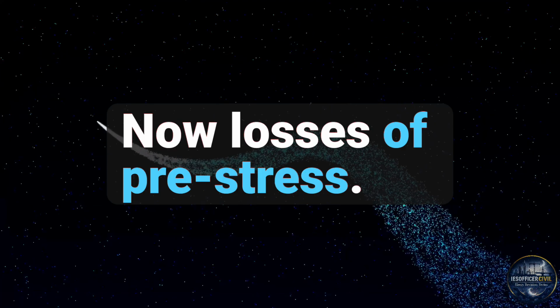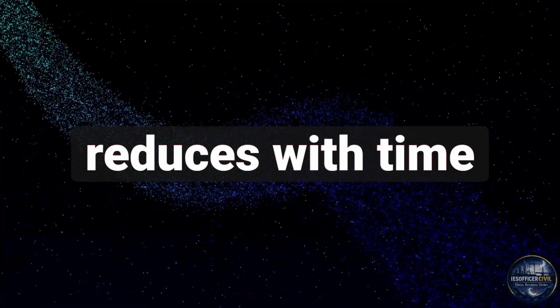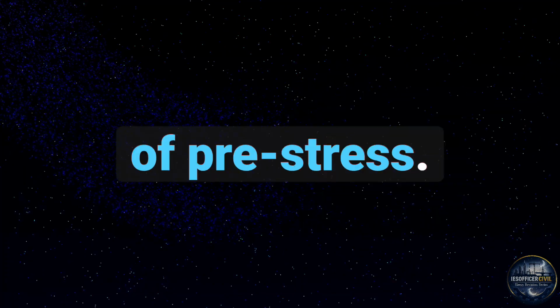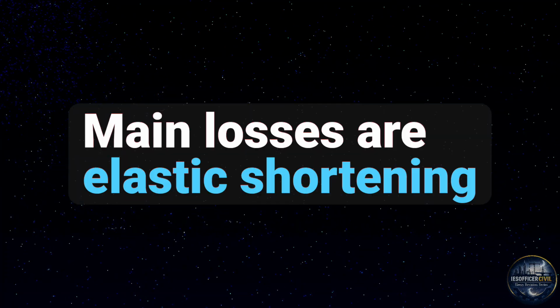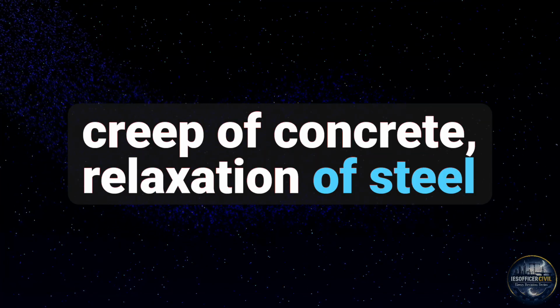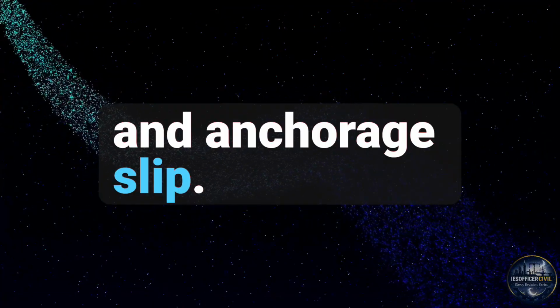Now losses of prestress. Prestressing force gradually reduces with time. These reductions are called losses of prestress. Main losses are elastic shortening, shrinkage of concrete, creep of concrete, relaxation of steel, friction loss, and anchorage slip.